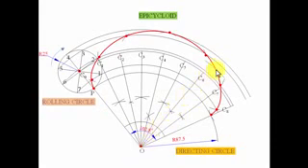Let's say this point is named Q. With Q as the center, somewhere along this arc, we put an arc yet again with a radius of 25 millimeters, small r. Small r corresponds to the rolling circle radius. So with Q as center, I'll put an arc over here, something like this. This point is S, and the next thing to be done is to join S with O. On drawing this line, you should realize that the surface on which the circle is rolling is intersected somewhere here.